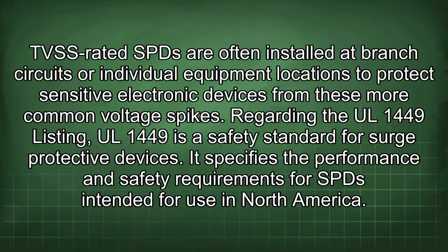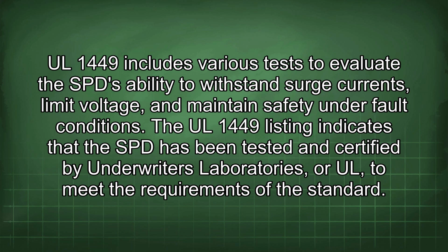It specifies the performance and safety requirements for an SPD intended for use in North America. UL 1449 includes various tests to evaluate the SPD's ability to withstand surge currents, limit voltage, and maintain safety under fault conditions. The UL 1449 listing indicates that the SPD has been tested and certified by Underwriters Laboratories, or UL, to meet the requirements of the standard.